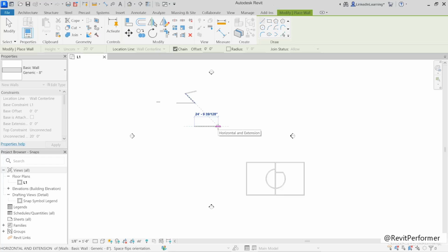And notice that it just goes down to this really fine fractional increment the minute I did that, right? So if I come over here a little further, and go back right there, it goes really fine, and really fine, or the same thing over here, really fine. So the increment snaps only apply when there's nothing else nearby that's more precise.